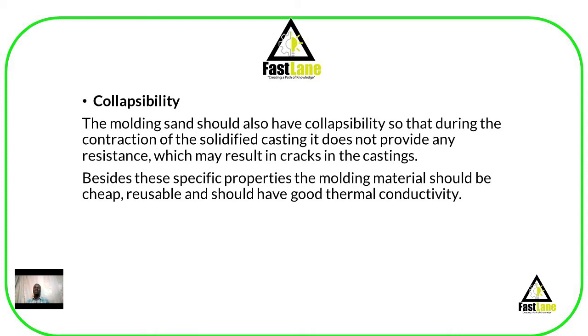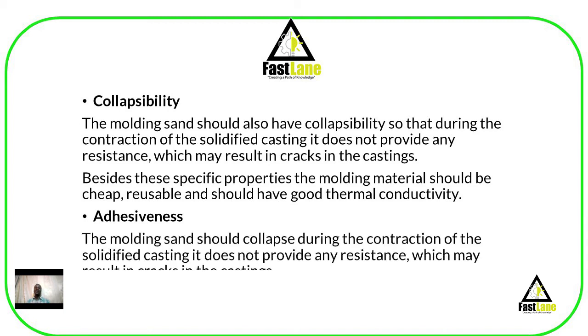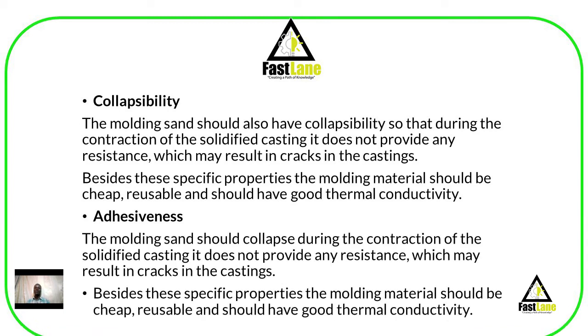Then we have other properties that may not be taken into consideration, although they are very essential when it comes to creating a sound molding sand. We have what we call adhesiveness. These work hand in hand with collapsibility. So the molding sand should collapse during the contraction of the solidified casting.